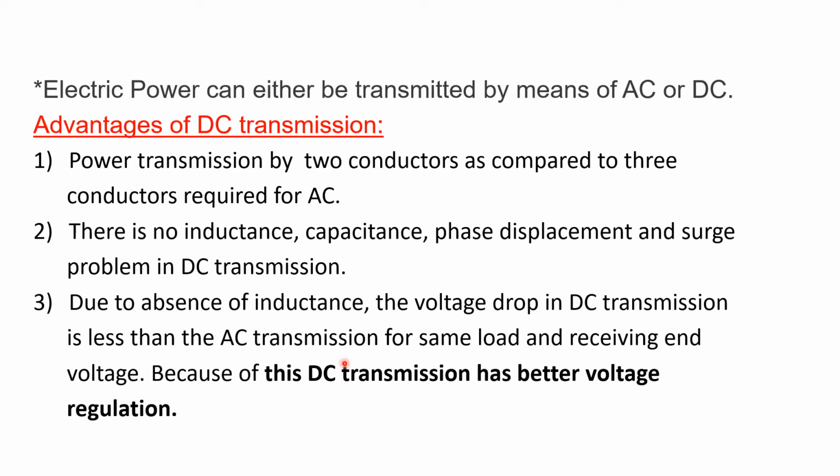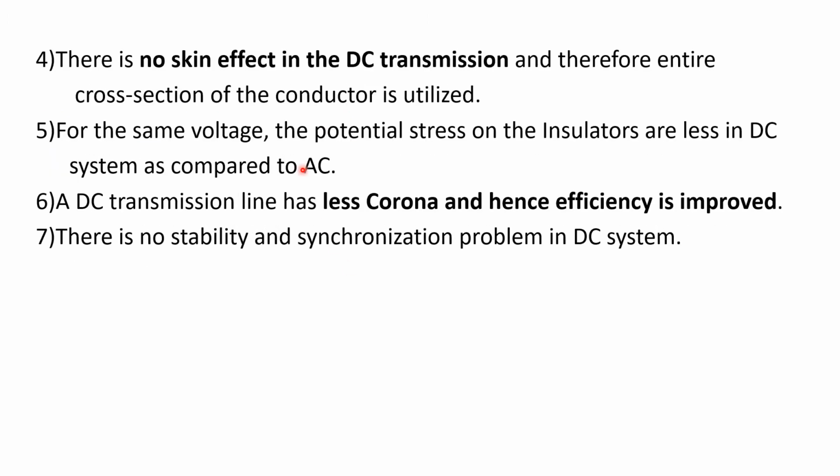This point is very important for technical exams. And the fourth point is that skin effect problems will be absent in DC transmission system, so that the entire cross-sectional area of the conductor can be completely utilized. That is one of the major advantages of DC transmission system.